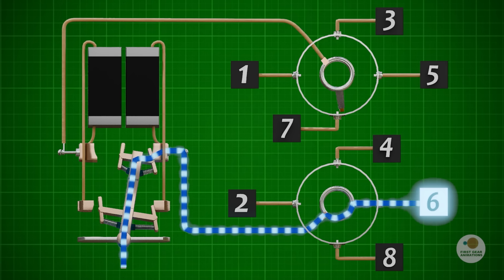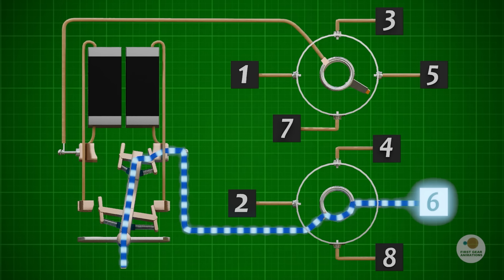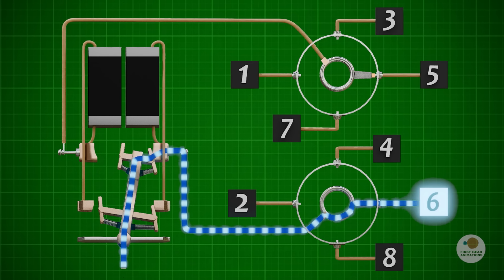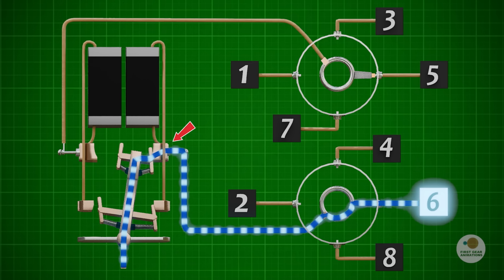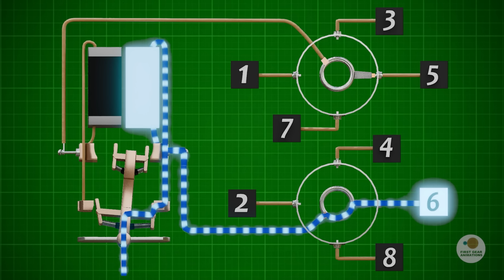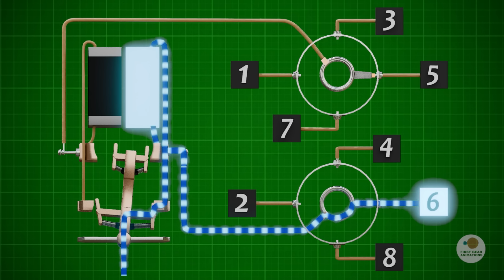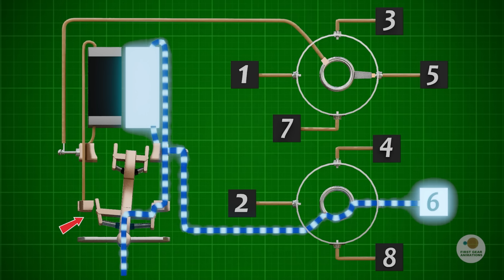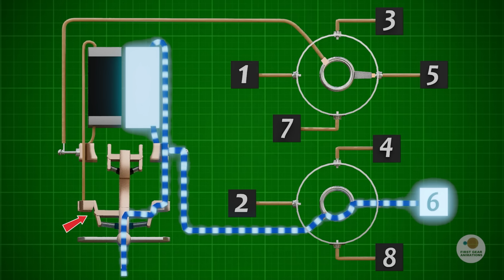During this critical moment, the diverter switch follows a precise sequence. First, it opens the connection to the old tap position 6. As it does so, it instantly inserts one transition resistor into the circuit. The full load current now flows safely through this resistor. Next, the diverter moves into a very brief intermediate bridging position.